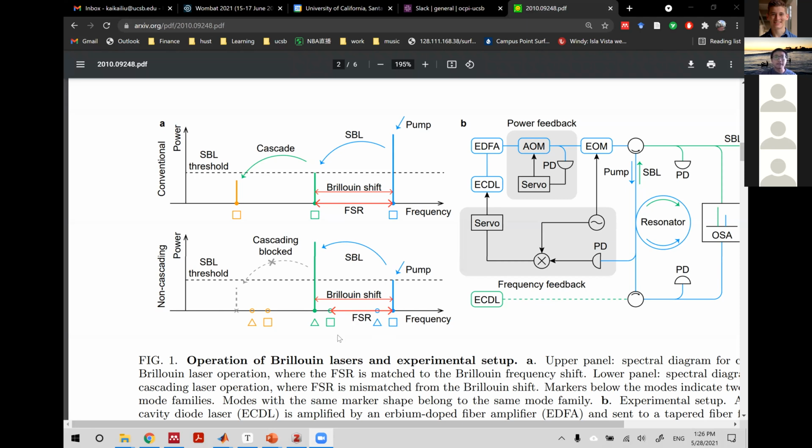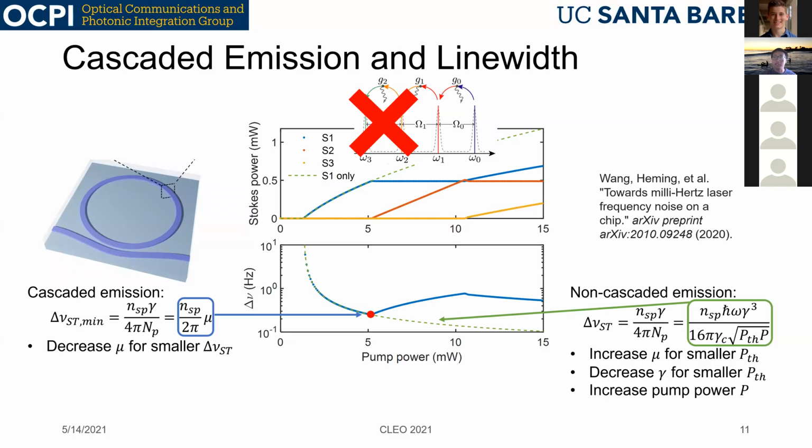And I think you also asked how we're going to achieve the suppression of the second order. What we're going to do is split the resonance where the S2 sits. You can add splitting by putting gradients on the resonator waveguide, or you can couple another resonator with the resonator so that you can split certain resonances. That's what we're thinking right now to achieve the similar thing, so that we can keep narrowing the Brillouin laser emission, which is very tempting to do.